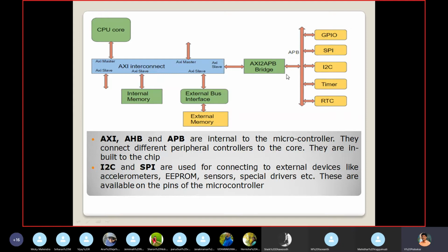So it will be received here, and here we have a bridge. That will convert the APB or AHB into the AXI protocol. Okay, those signals are mapped with the AXI signals. Then through this AXI signal interface, it can reach the processor, a controller or a DMA, those things.